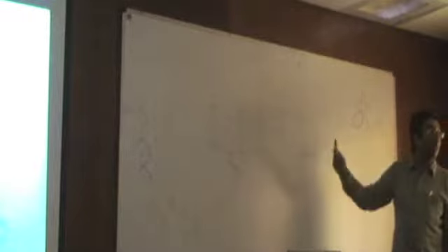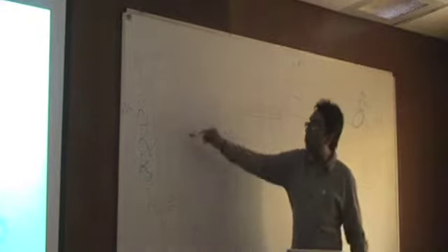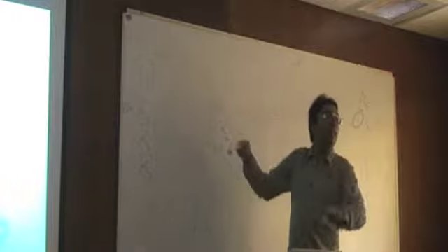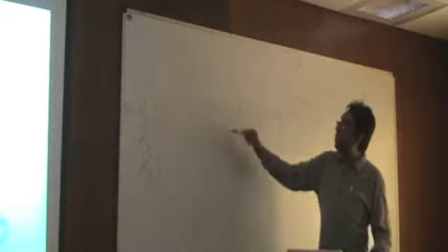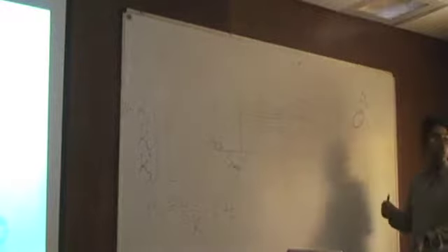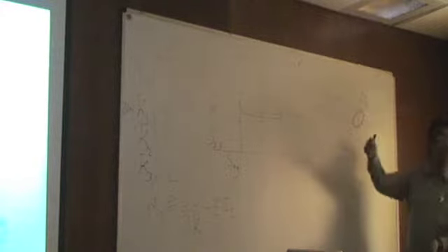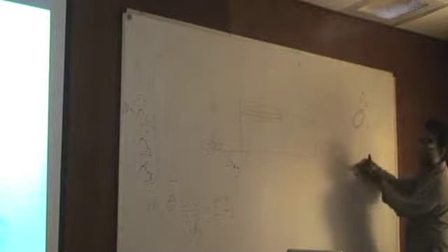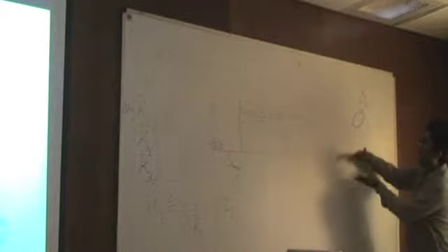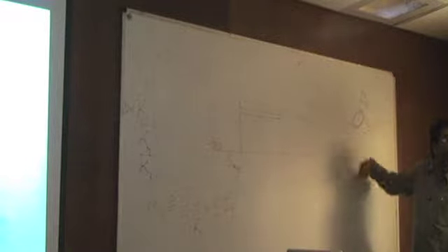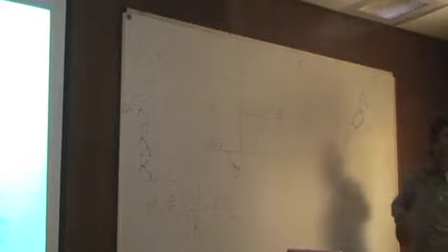So because we have substituted these warpings into the energy, they are in terms of your kappa 2 and kappa 3, and when we integrate that over the cross section, that basically says that as W2 or W3 are non-zero, that's going to change your S33 bar, S44 bar. In this particular case, because of the way this W3 is, it primarily reduces the moment of inertia about this, and in turn reduces the bending stiffness.